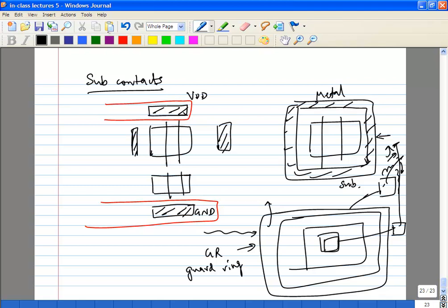So it depends on a number of things. It depends on the surrounding environment. It depends on this circuit itself. So I'll give you an example. If you just take a switching inverter, it is going to be pumping something into the substrate. If you connect it to its own ground, you want to keep its ground clean, okay, for the inverter to switch well. If you connect it to its own ground, you may end up spoiling your own inverter switching characteristic. So there you may have to be careful.